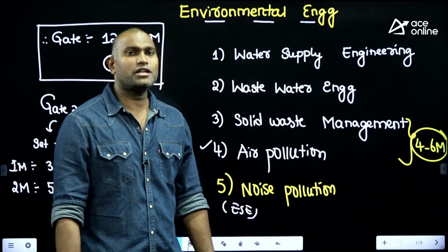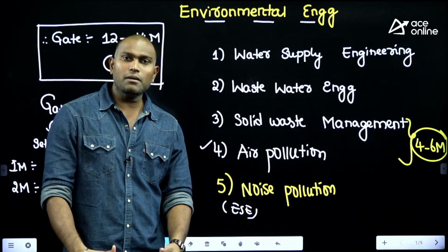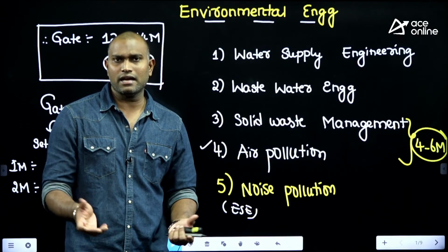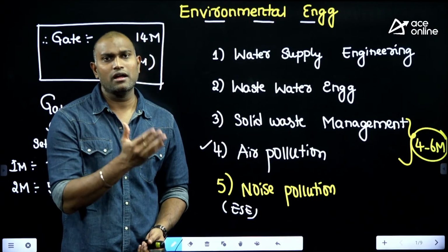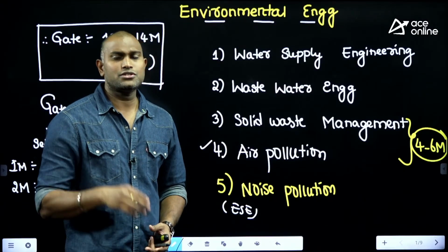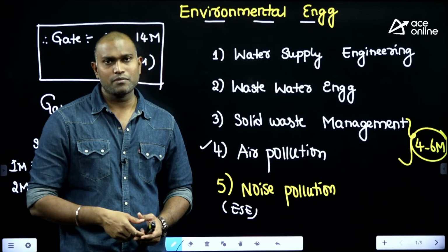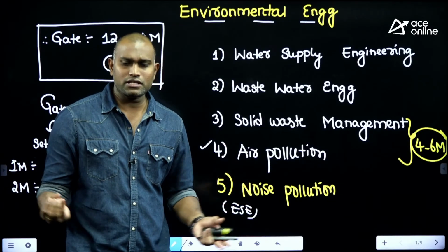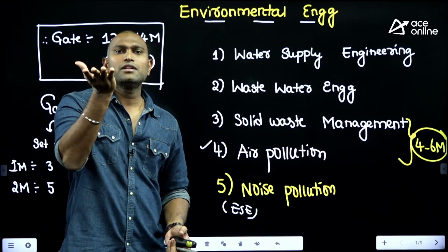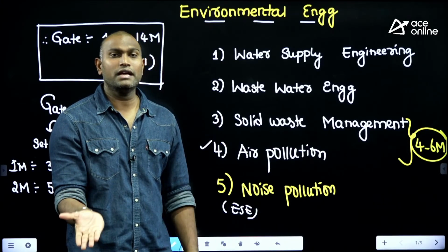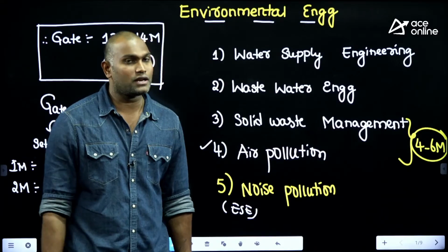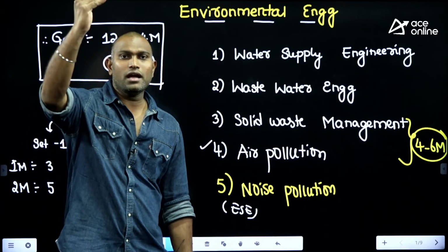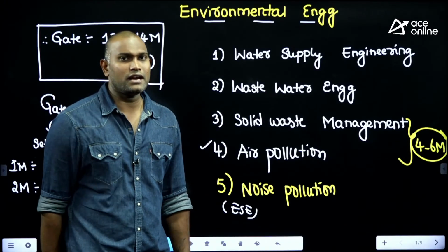Number 3, based on the lapse rate. As we deal majorly with the troposphere, there is the environmental lapse rate, which depends upon the surrounding temperature, climatic conditions and topography. And one more lapse rate, the adiabatic lapse rate. Irrespective of the surroundings, when you release a hot air sample, its temperature decreases by 9.8 degrees centigrade for every 1 kilometer, until it becomes a condensate, and beyond that it reduces by 6 degrees centigrade for 1 kilometer.